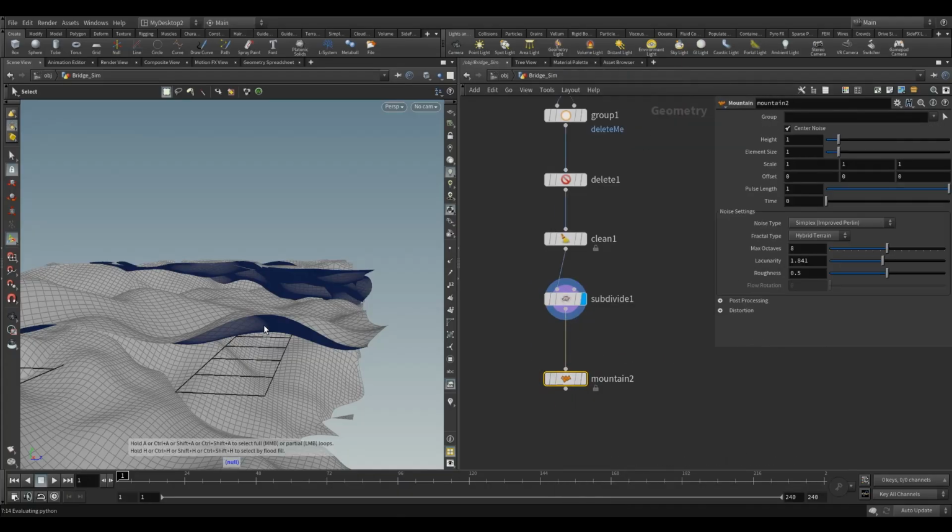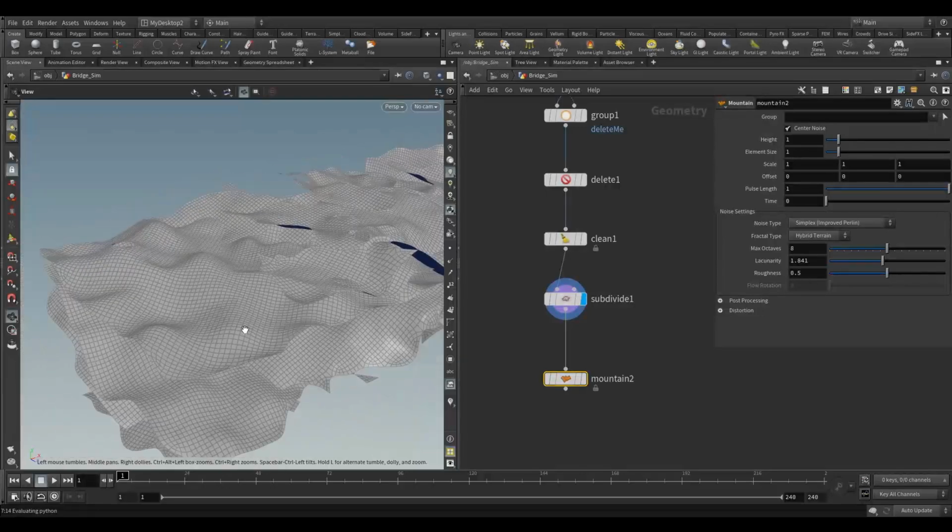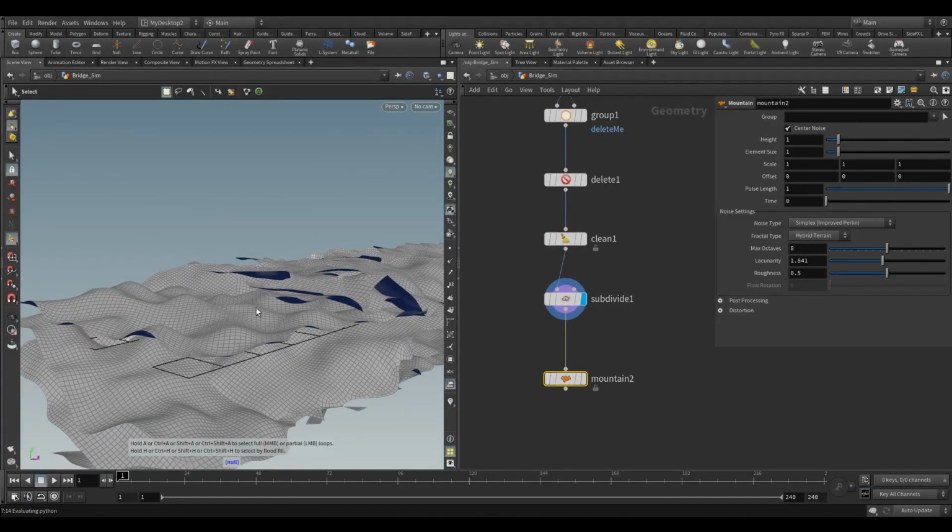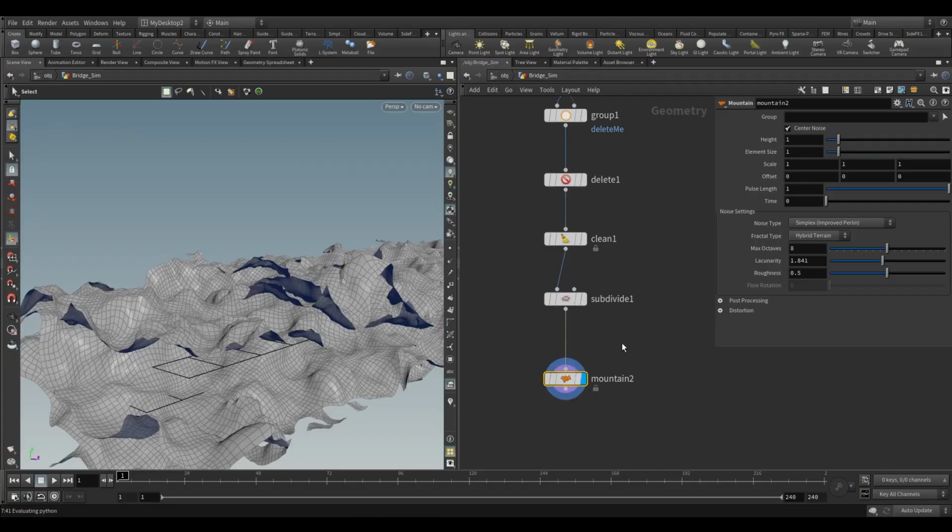It's a good idea to achieve lifelike, believable results. Typically, when you're looking at noise, you're looking at it in stages, like big noise, smaller noise, maybe at least typically 3 layers of noise. That's whether it's fracturing something, or the disturbance in a volume, or textures, things like that.